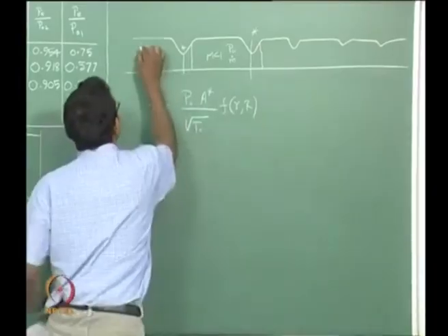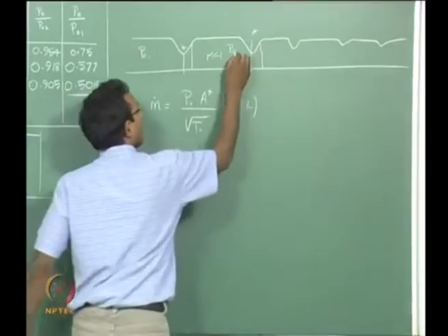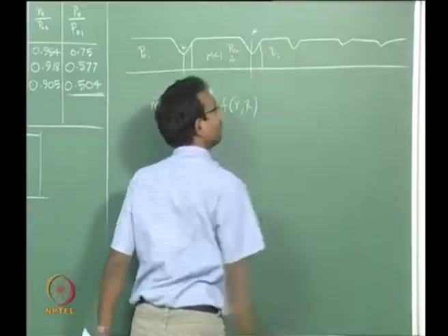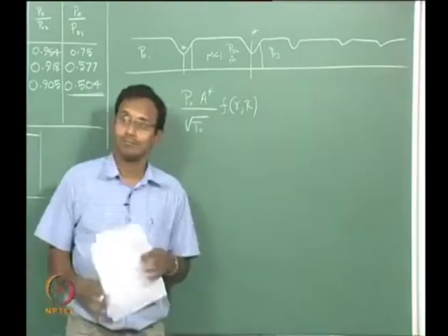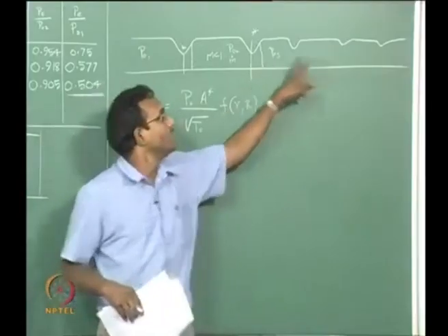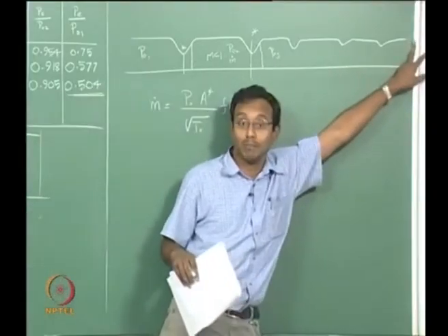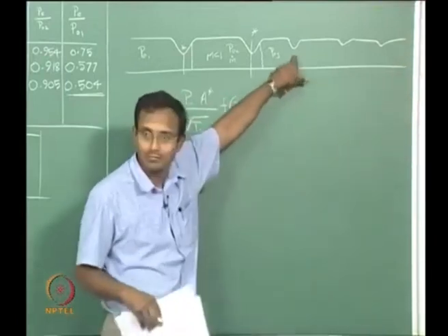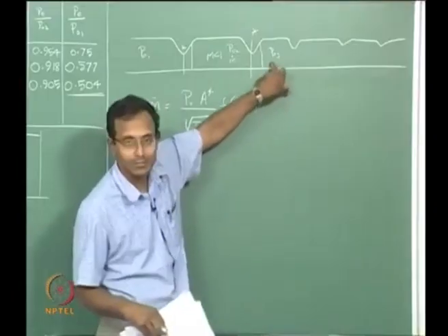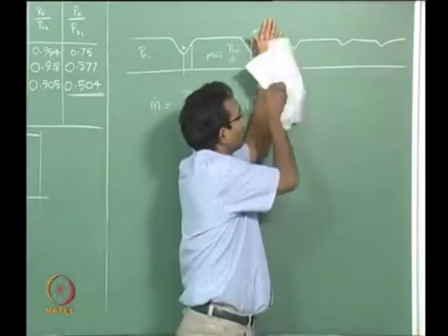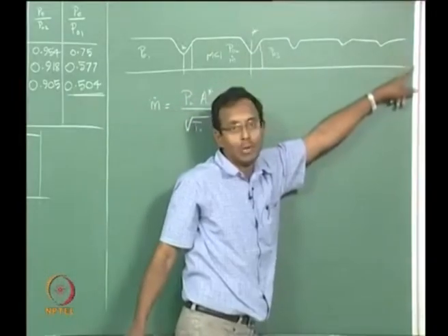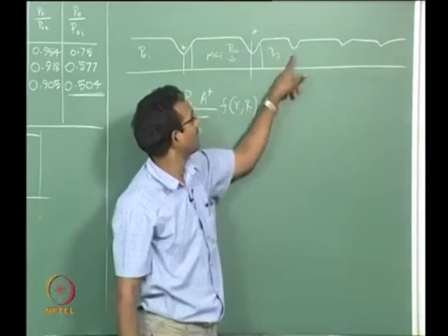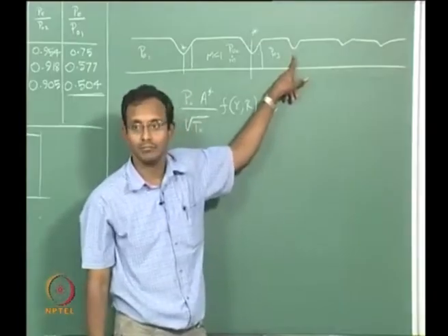Okay, we will make it numbered P01, P02. Now I have a P03. That is a possibility. Now if I decrease my pressure further downstream, P back really low, then I can still make it choked here. For this P0, I just look at this problem from this point on downstream. If I make my PB low enough for this particular P03, then this condition may get choked, right.